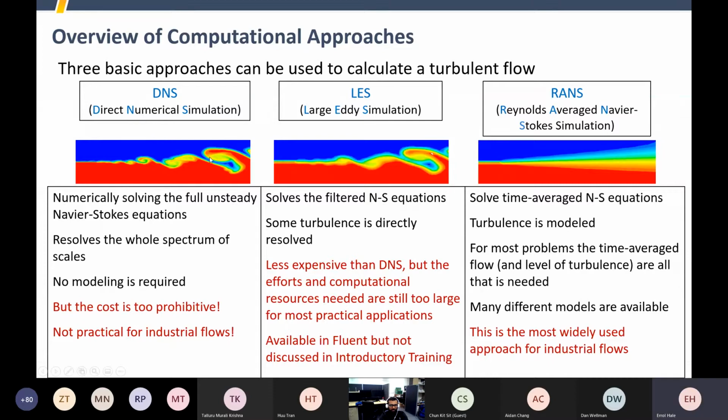So it becomes really important to be able to capture the bulk effects of the turbulence in an averaged manner, because then that allows us to get a higher level of accuracy. So we'll go further into what it means in the boundary layer later on, but one example of that is if we were to model this here, we'd need to pick up this turbulent vortex structure, we'd need at least, say, 10 mesh elements across that thickness, across the distance of that vortex in order to pick it up properly.